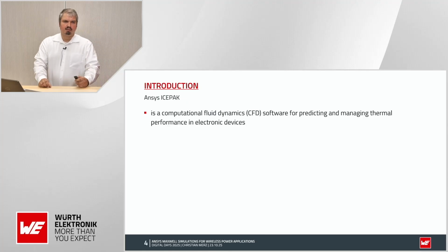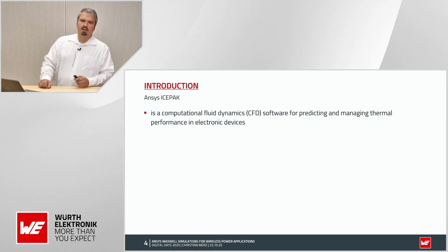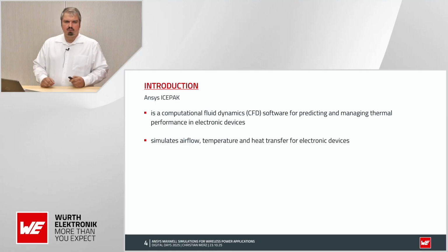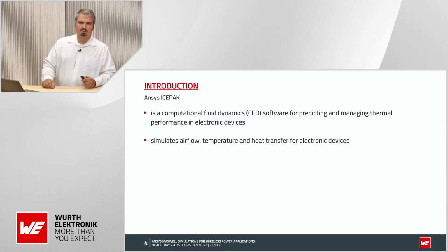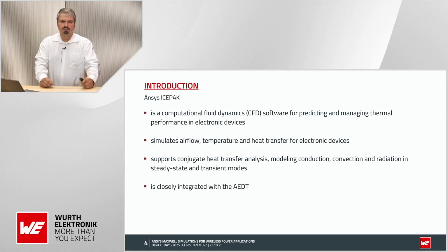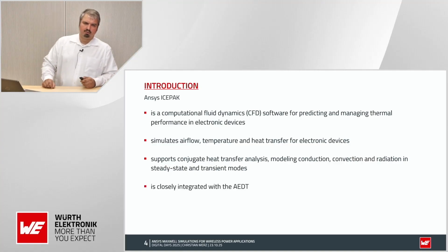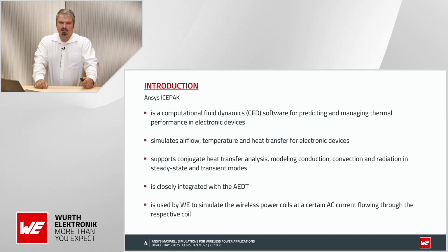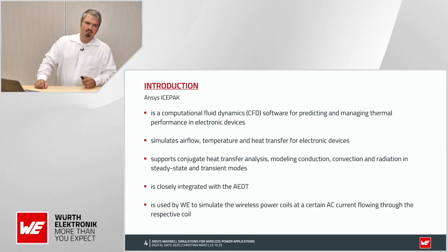What is ICEPAK? ICEPAK is a computational fluid dynamics software for predicting and managing thermal performance in electronic devices. It simulates airflow, temperature, and heat transfer for electronic devices. It can model conduction, convection, and radiation in steady state and transient. It is also integrated into the Ansys Electronics Desktop and is used by us to simulate the wireless power coils at a certain AC current flowing through the respective coil at a certain frequency.